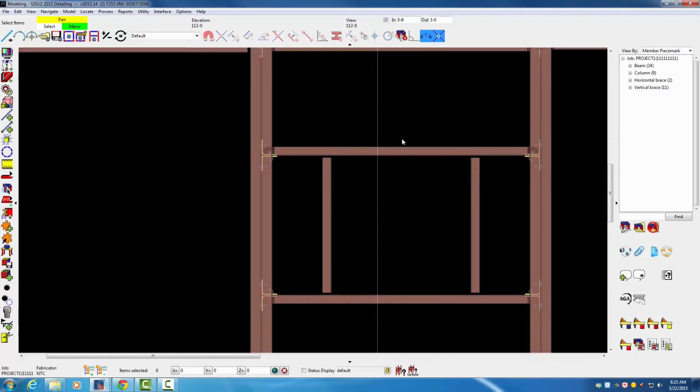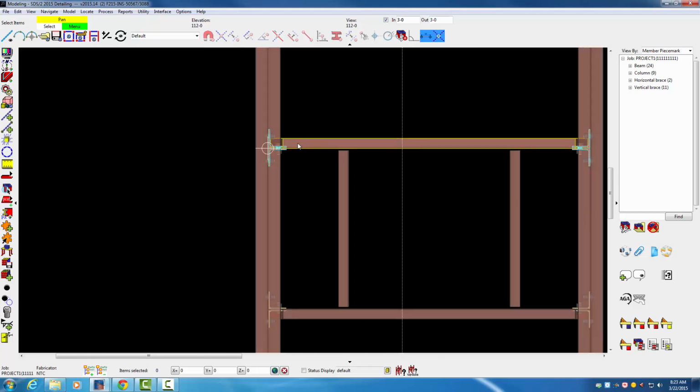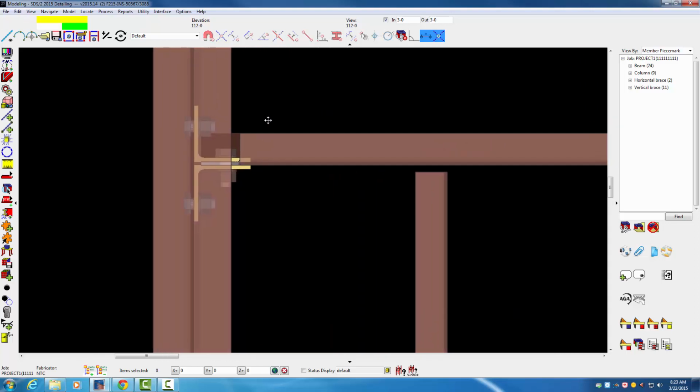channels. As you can see on your drawings, again, it shows a little L shape for a clip angle. As I zoom in here on my screen for this particular connection, you can see I've got my model shown in solids and transparent mode, so I can see my clip angles. And I have a clip angle here on the far side and here on the near side. On your drawings on S2, it is shown that we only want this clip angle here on the near side, and we are going to make that a welded connection.